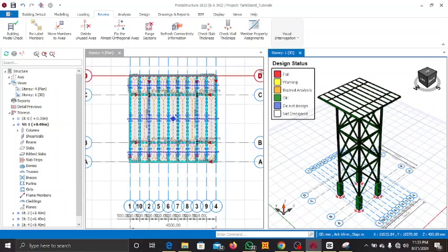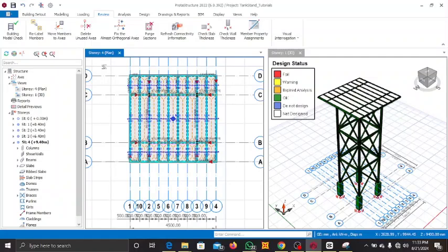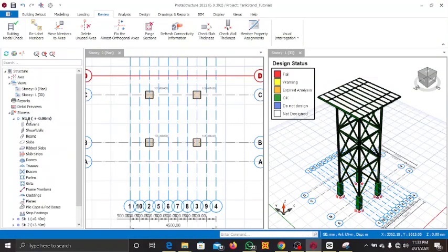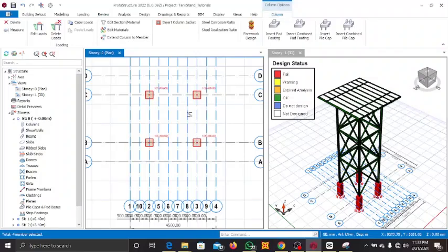The next thing we are going to be adding is going to be the pad base, the footing for our tank stand. So you're going to come here, click on your plan view, come to Asterisk 0. You can highlight all and insert pad footing.